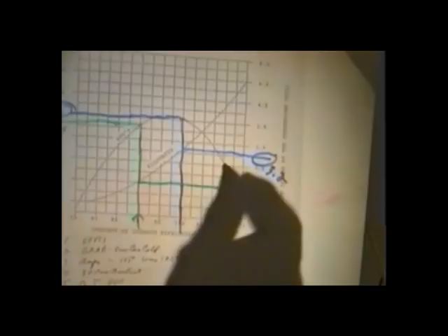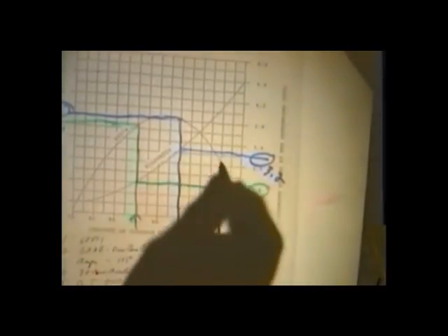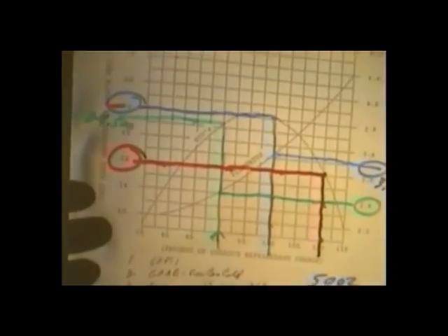10%, gentlemen, 110% of the charge. Here we go. Let's run up here to the BTU line. Do you notice that's the BTU line? Look at this. Now we come all the way over here. Now we've got an 18,000 BTU AC. Now look at the capacity that we lost by being 10% overcharged.